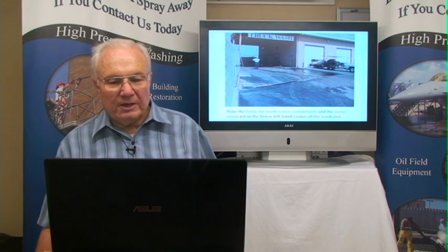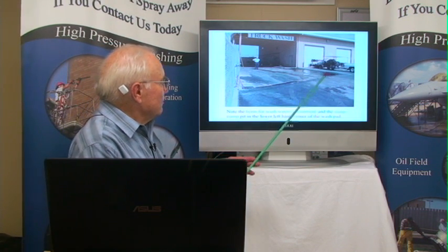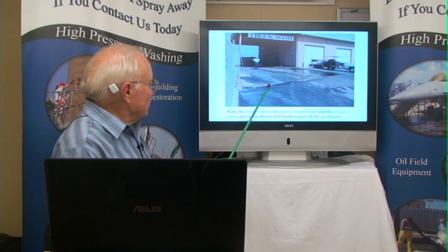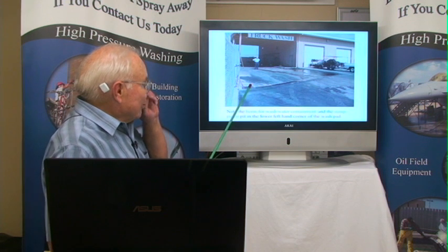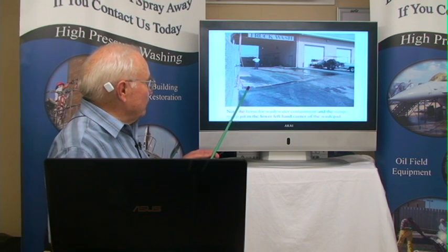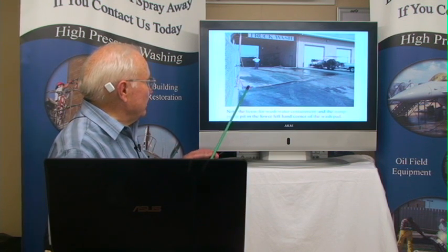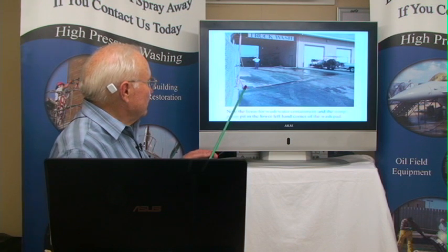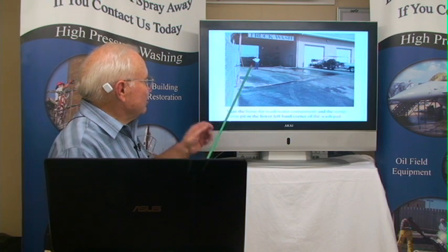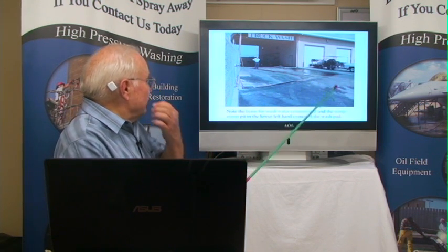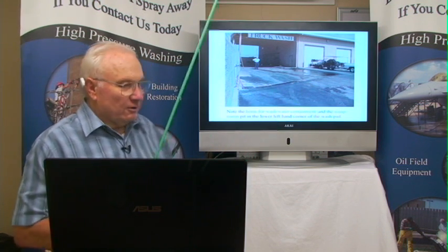This is a truck wash bay, and what they've done is run a berm right here, if you look, and then they've got the drain there. That's actually not a drain. That's a drain, all right, but it only goes down. It's about a 10-gallon, maybe 15-gallon drain with a sump pump set into it. It pumps the water up to the sand trap in the middle of that bay. This has recently been expanded to an all-concrete surface instead of asphalt.